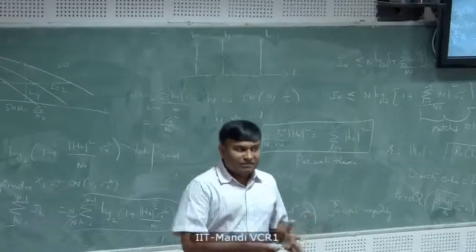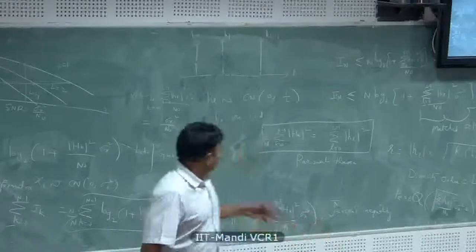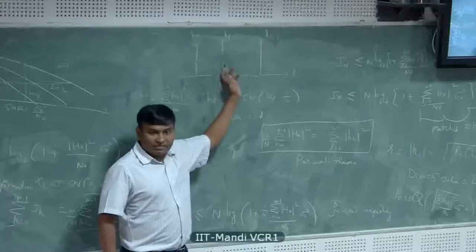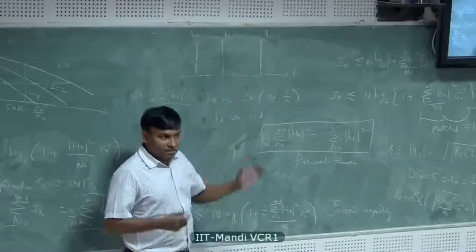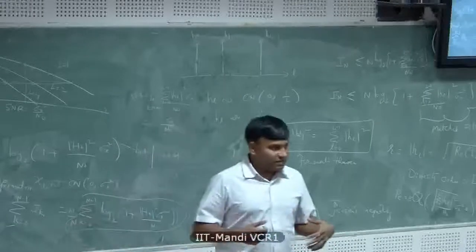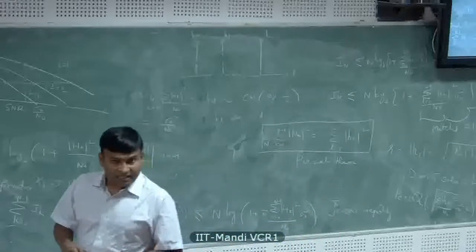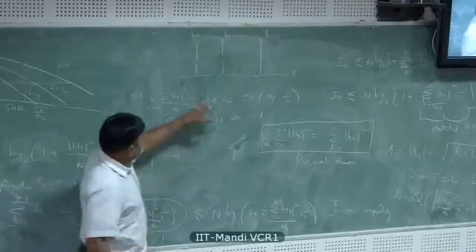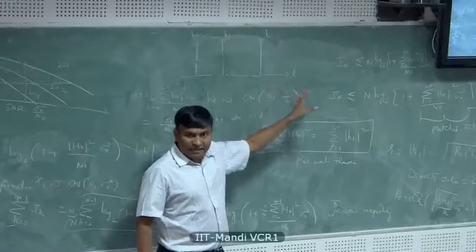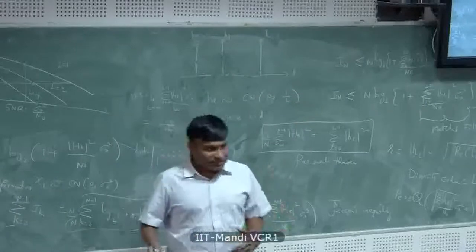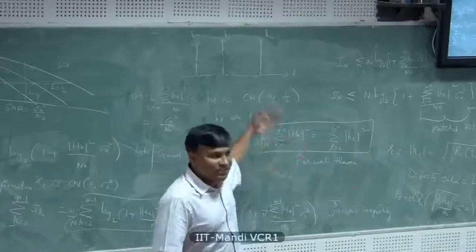But generally, when the bandwidth is so high, 20 megahertz, you can safely assume that there is enough multipath that you're not diversity starved. There is enough diversity for the link. Okay. There is really no reason why you should put multiple antennas and give transmit diversity or receive diversity when the channel has so much diversity built in.